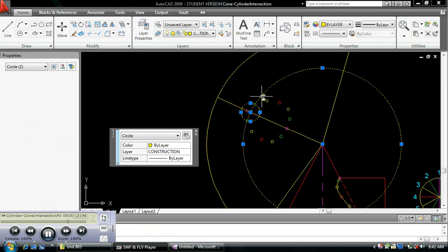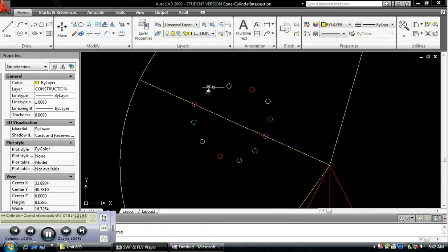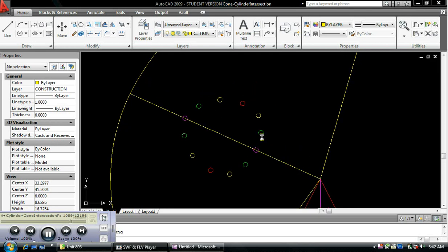And when you get done with your work, check and make sure that you have some symmetry like this. It's not going to be a circle, of course, but it should be similar to this shape. The reason you want to do this is you want to make sure that you transferred your arc lengths correctly, and you may actually want to write them down as you transfer it. It'll decrease the chance for error.